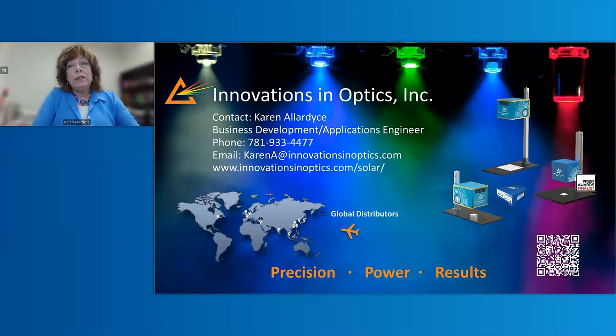For all of our LumiSuns, well, I shouldn't say all right now, but for most of the LumiSuns, we cover the AM0 and the AM 1.5G. So in particular, for the LumiSun 220, yes, that will be a feature of both, in fact. And it is class AAA plus with low spectral deviation. So you'll be able to test a range of samples, both under space conditions or UV testing, perhaps, and also under the Earth's conditions at terrestrial AM 1.5G.